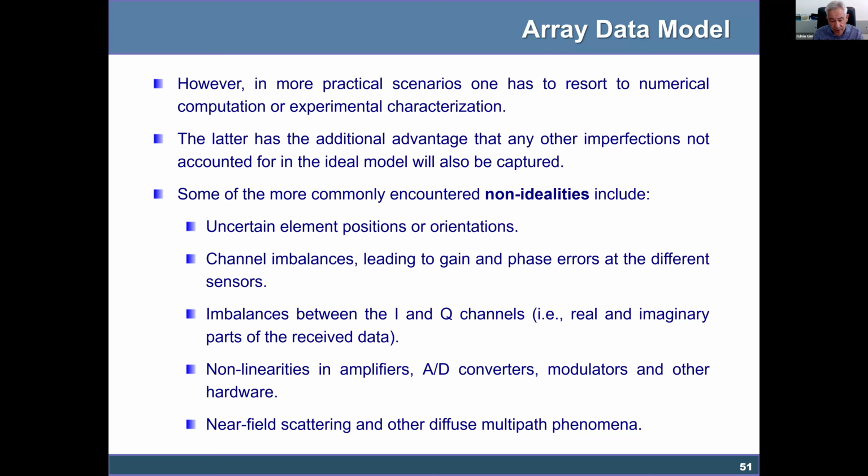The two low-pass filters should be exactly the same, and maybe they are only nominally the same. Another source of non-ideality is that the filters, and in particular the amplifiers, do not behave exactly as linear time invariant systems, but they can introduce nonlinear distortion.